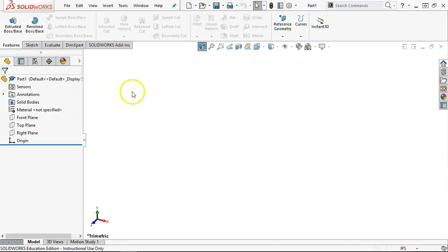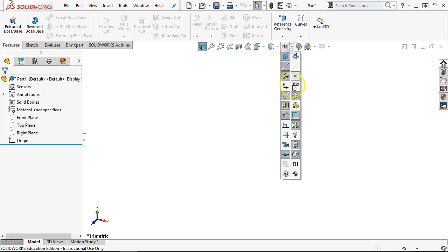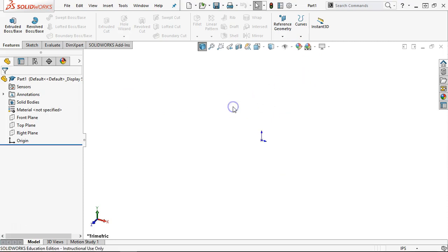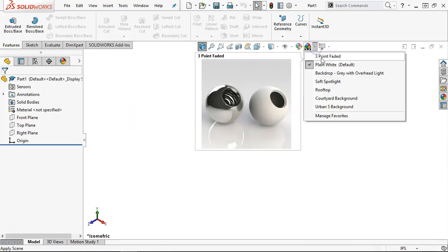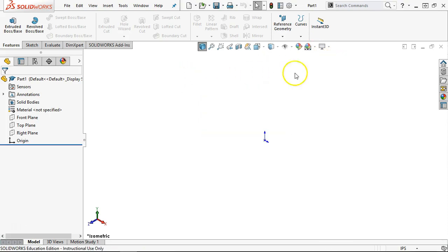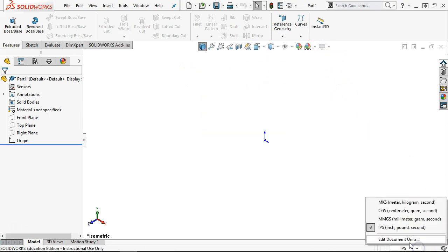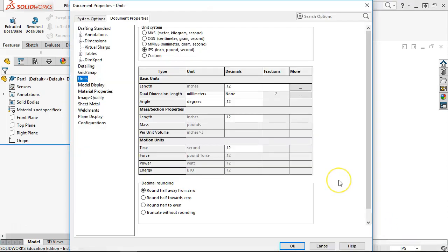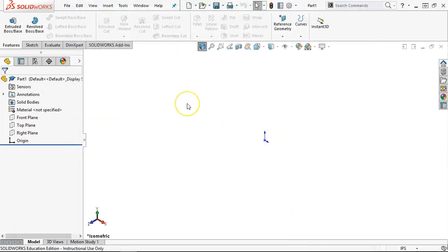We ran through the process of setting the things that we like. So turning the origin on. I want my template to have an isometric view to start. We set our default, the plain white, and went through and set a couple of options for units. I'm going to give you the 3 or 4 big ones that you would want to change. So, inch units to 3 decimal places. And then we hit OK. There will be a few more that you would want to build in.